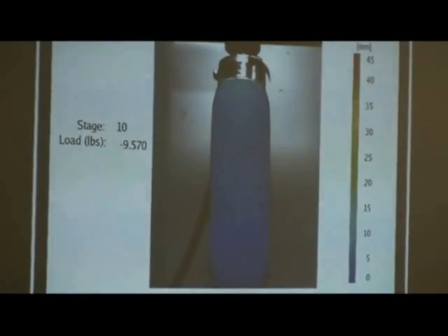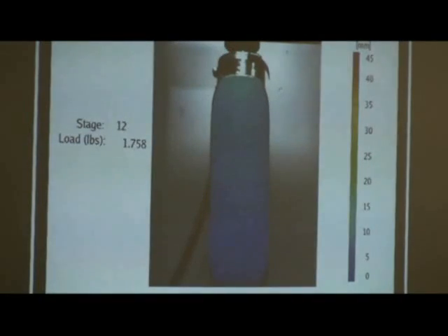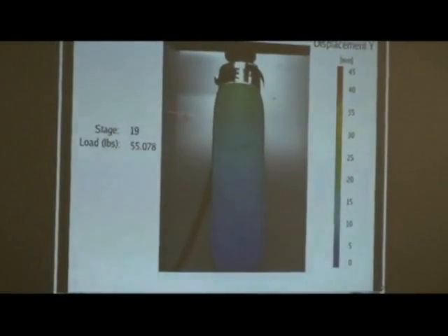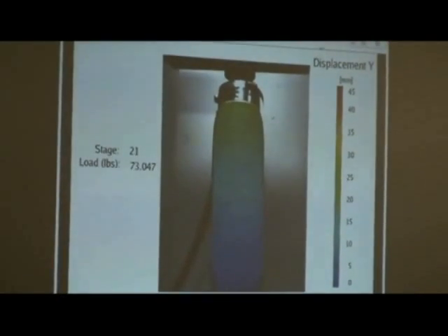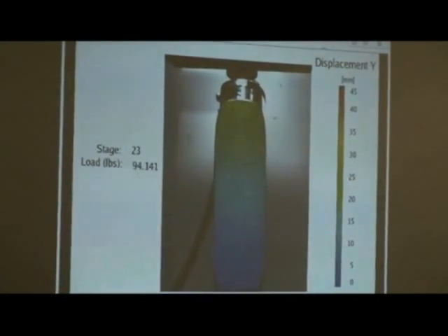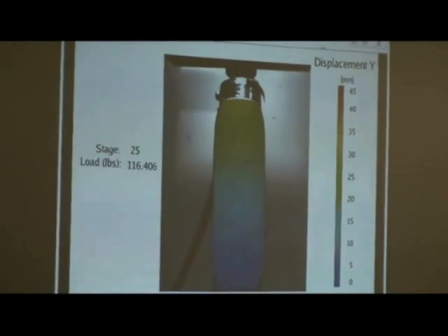This is a mechanical testing machine. The crosshead is moving up, and as it moves up, we're measuring the displacement. You can see the little white dots on the cover, the pattern that we applied to it. And from that, as this tensile test is being applied, we're measuring the displacement.